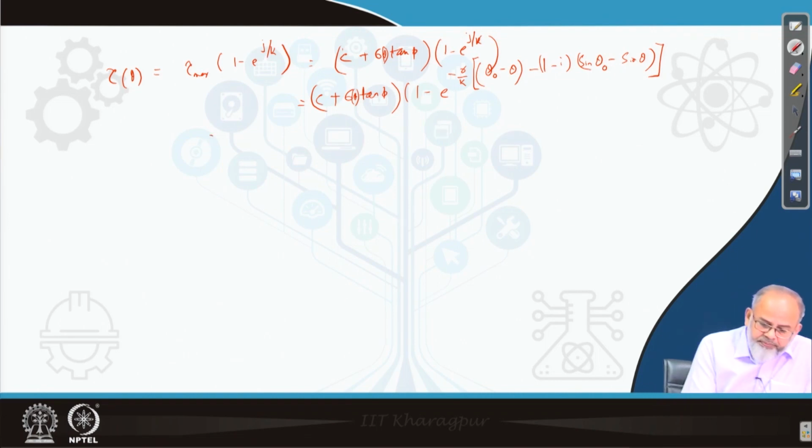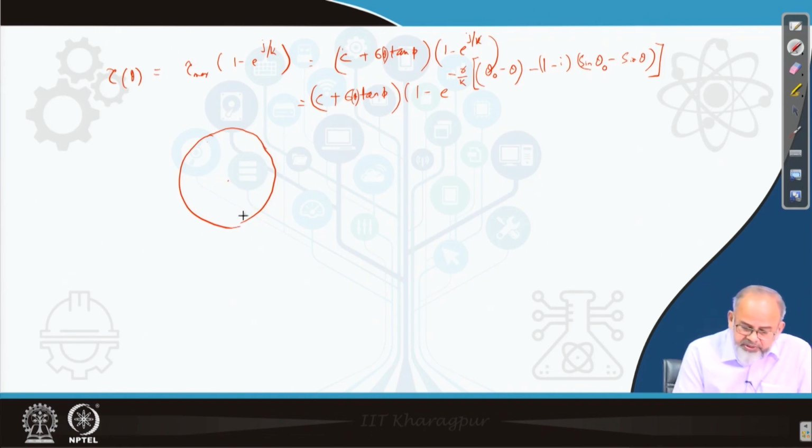Now, in a rigid wheel, what you are interested in developing is the thrust force. So now the shear stress, suppose this is the soil surface. Now, the stress which is developed, from there we will find out what is the shear force which is acting. Shear force will be like this. So, shear force will be equal to the shear stress into area.